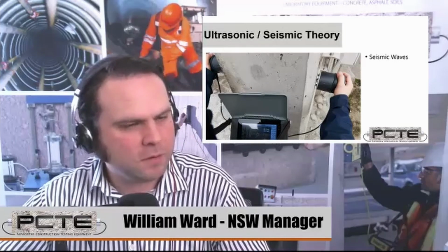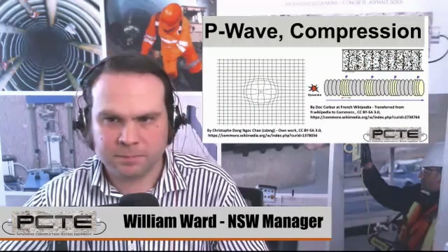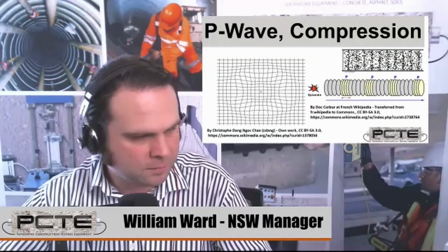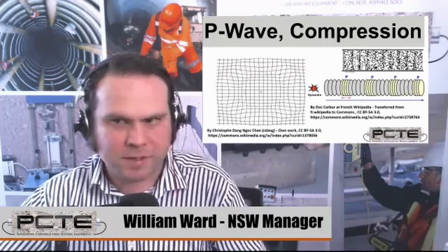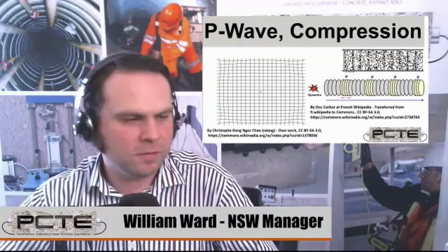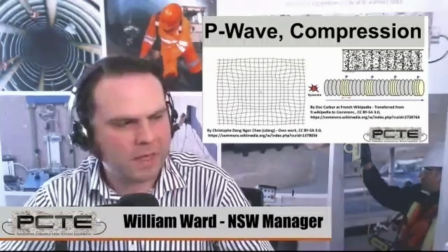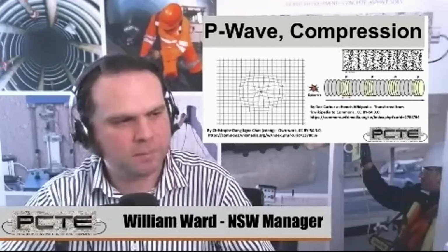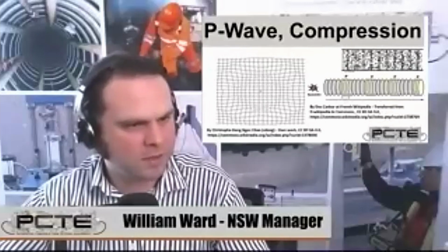So before we go on to techniques, just a few notes about some of the different forms of sonic or seismic energy we'll discuss. The most commonly used energy is sound waves, or P waves, or compression waves. You can see in the animation that these move as a compression and tension wave from the point of origin. And this is what we hear as sound when we speak. So techniques such as impact echo, ultrasonic pulse velocity, and sonic echo or the pile integrity test take advantage of these compression waves in various frequencies and in various simple or complex applications of the energy.